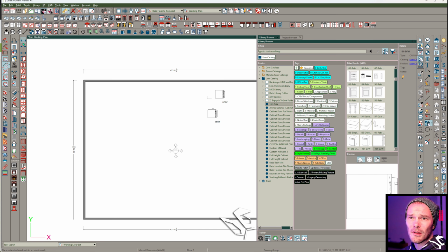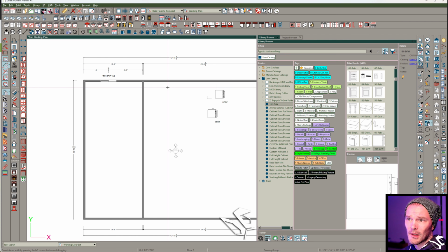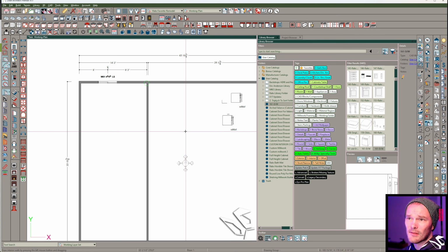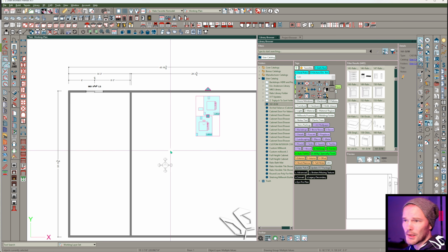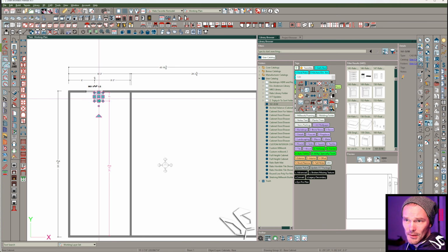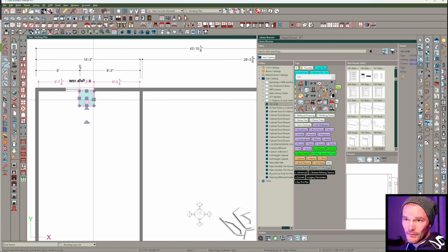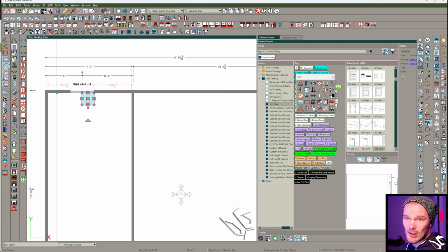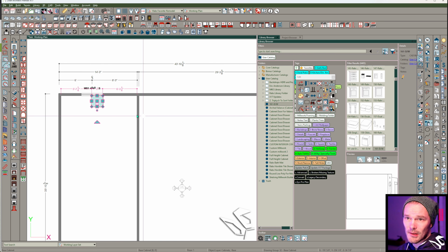I have mine set up so that I'm doing auto exterior dimensions, and I'm doing this in a very specific way. I'm picking up both sides of my interior wall as opposed to interior wall centers, and then for temp dimensions, especially if I'm throwing in cabinets or something like that, this is going to reference inside surface. So my exterior dimensions, because I'm largely in a remodel workflow, are referencing the main layer.